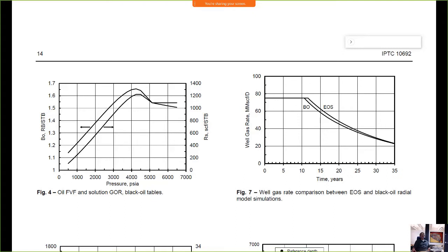But often you don't see the actual incipient oil because there is none. In the lab, the first liquid drop out here at 4,500 pounds, you don't take that out and analyze the composition. So you never see it from lab data, but this is always going to be the case. The leaner the condensate, the heavier that incipient oil is going to usually be in general. So it's not unexpected, and it is, I think, real.